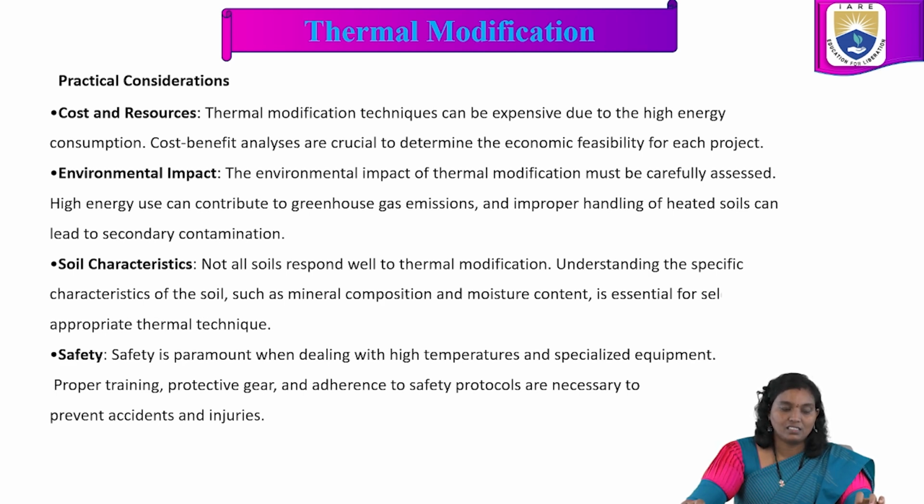Soil characteristics. Not all soils respond well to thermal modification. Understanding the specific characteristics of the soil, such as mineral composition and moisture content, is essential for selecting the appropriate thermal technique. Safety. Safety is one of the important parameters in thermal modification.